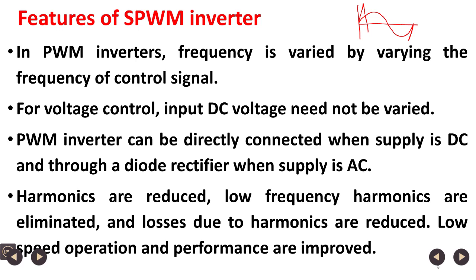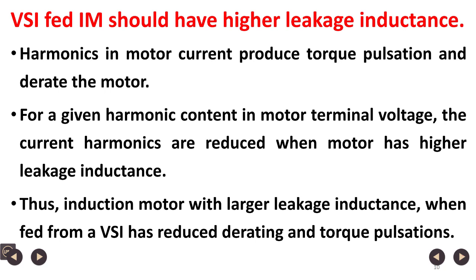Harmonics are reduced, low frequency harmonics are eliminated, losses due to harmonics are reduced, and low speed operation and performance are improved. So, sinusoidal PWM inverter is much better for induction motor than stepped wave VSI. Then, a VSI fed induction motor should have higher leakage inductance.